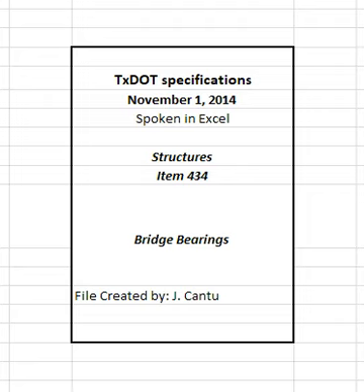Fit the PTFE material into the recessed surface with not more than 1/32 inches gaps around the perimeter. Perform required welding in accordance with Item 441, Steel Structures. Manufacture guide bars when required so that adjacent top and bottom bar surfaces are parallel to within 1/16 inches in the assembled position. The tolerance for diameter of anchor bolt holes is plus 1/8 inches, minus 0 inches.